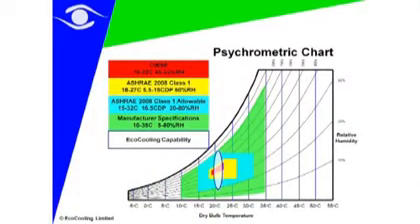But ASHRAE also gives us a little bit of latitude, and that's the design conditions. ASHRAE also provides an allowable zone which you're allowed to drift into for a short space of time. Now you see, this zone that we need to operate within, even to operate the very highest level of reliability data centers, is really starting to grow. If you look at your equipment, that's a typical specification for modern equipment. Really quite a wide range.